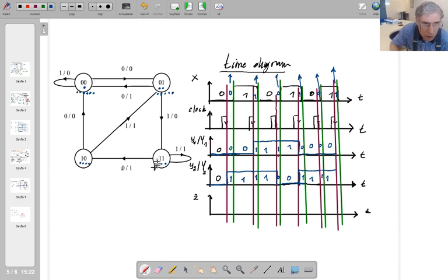So that was the beginning, was this, isn't it? So in this state, you are applying 0, your output is 0 here. Before the clock pulse, you're going to see that set value. Why is that? Because of the combinational circuit. If you know the present state, if you know the input, that is the output. That output is the output of a combinational circuit. Therefore, before the clock pulse, you're going to see that output. So that output is going to be 0 until the clock pulse.